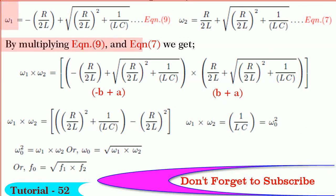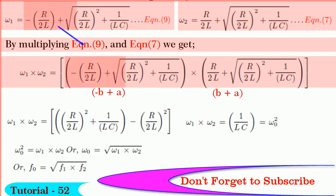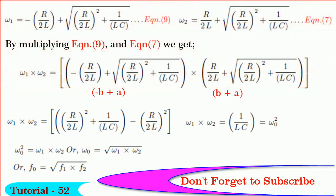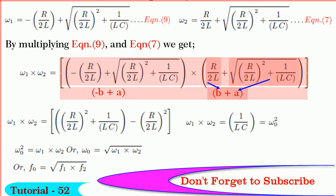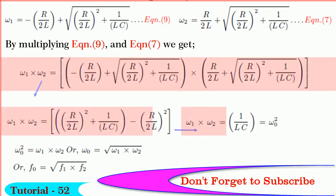By multiplying equations 9 and 7, we get omega 1 into omega 2 is equal to, in one bracket, minus R by 2L plus square root of (R by 2L) whole square plus 1 divided by LC, into, in another bracket, R by 2L plus square root of (R by 2L) whole square plus 1 divided by LC. You find that the right hand side of this equation is of the form (a plus b) into (a minus b). So, by solving, we get omega 1 into omega 2 is equal to 1 divided by LC.